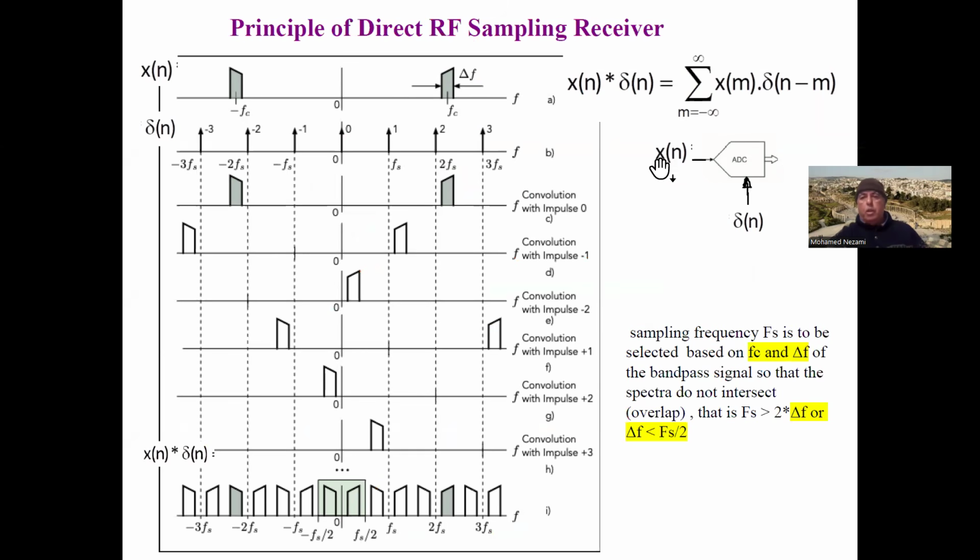You have the analog signal that you're trying to sample, and you have the sampling frequency that you drive the ADC with, okay? And usually this here is really a train of impulses that are uniformly spaced in time, because every time you pulse the ADC, basically on the rising edge or the falling edge, you're making a sample. And mathematically, that's really a convolution process.